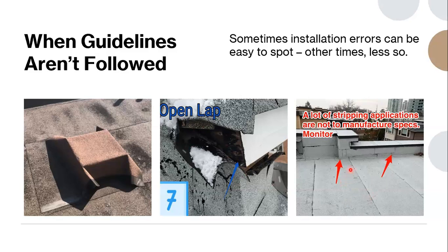If you look here, you can see that there's just a lot of little patches throughout. It's installed horizontally instead of vertically along the stripping. The runs aren't staggered here.